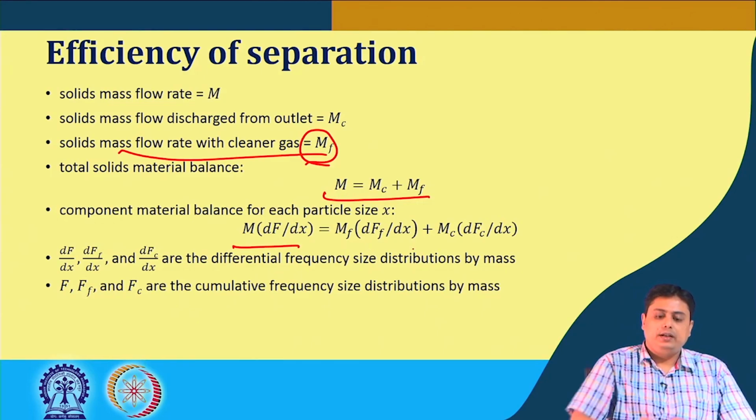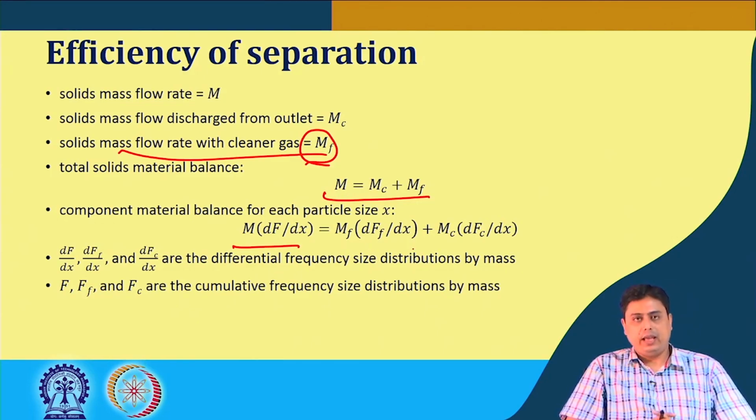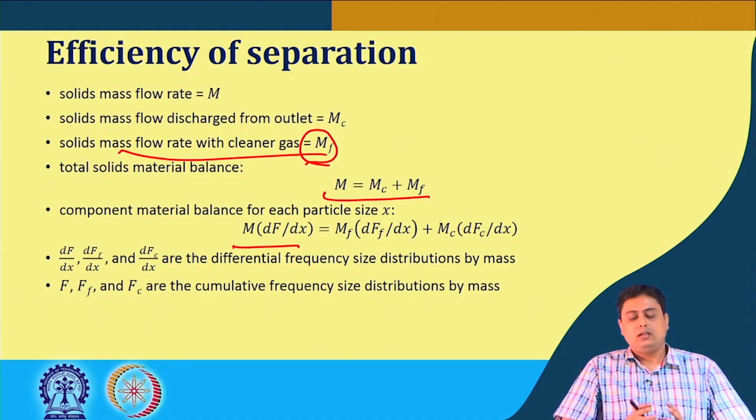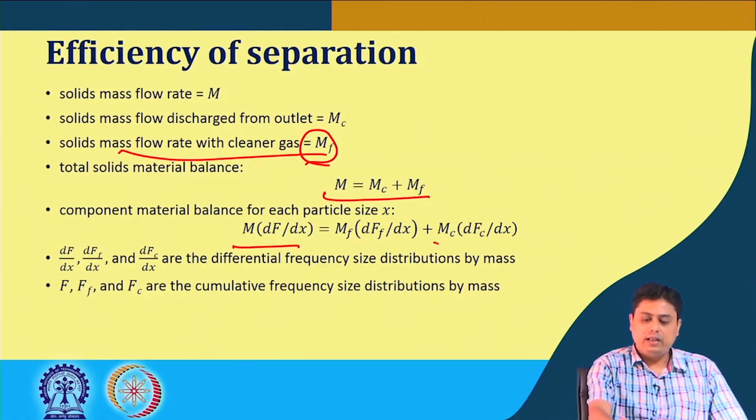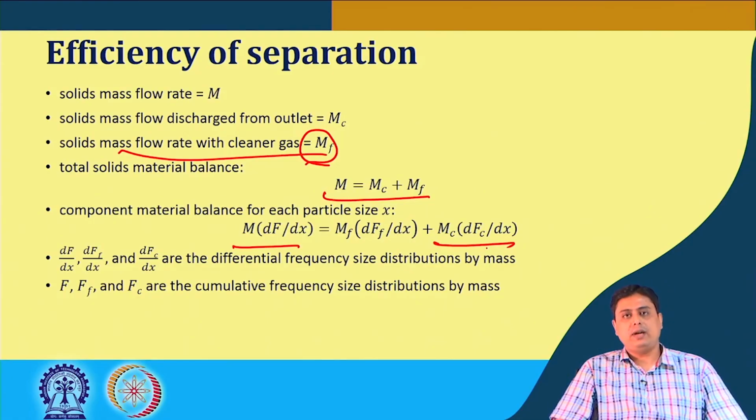Similarly, df_f/dx stands for the finer particles. This is the differential size distribution of the solids in the finer particle collection, or the clean gas collection outlet, and accordingly df_c/dx is the differential size distribution frequency by mass of the coarser particles.